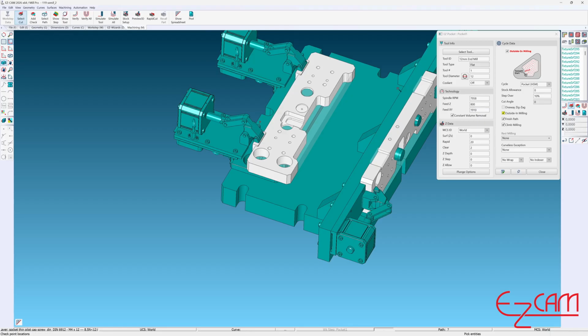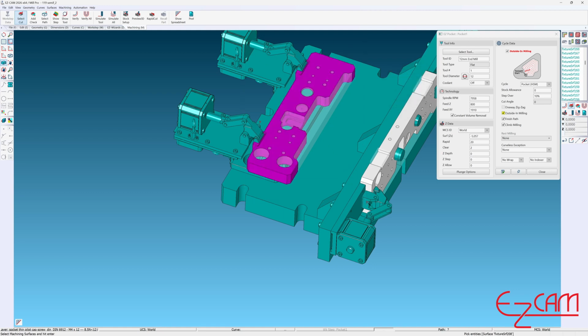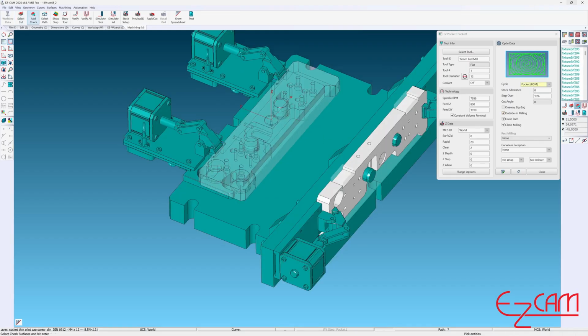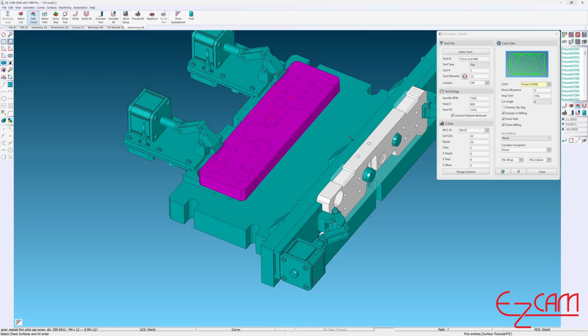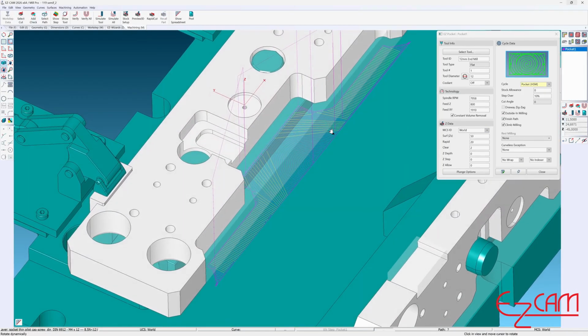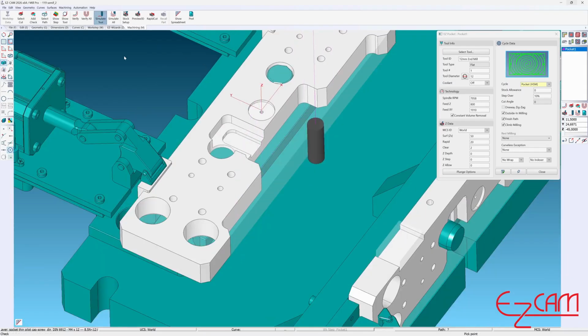After quickly checking all the information on the page, let's move on to surface selection. Machining surfaces in this step allow the user to partially select the regions to be machined on the part by using Smart Click. In my current example, the entire model needs to be selected, so I hold down the left mouse button and frame the whole model. Then on the right side, I can define to the program that I want the area between the stock and the part to be machined. For this, after clicking the Control Surface command and selecting the stock, we can check the result with Calculate Toolpath.